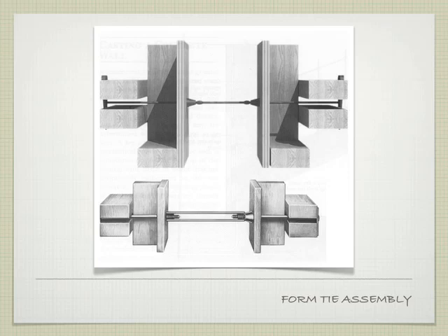That make sense? Yeah? So if we look at it here, this is the same thing that I'm showing. Here's this form tie, like that. That cone is held tight against this piece of plywood. Likewise, against this piece of plywood, we have our vertical stud, we have our horizontal wailers, and we have our metal clip on the outside that holds it a consistent distance apart.